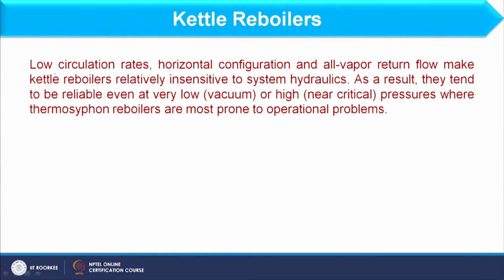So, these are some points about the kettle reboiler. Let us have more discussion about this. It has low circulation rates, and the horizontal configuration and all-vapor return flow make the kettle reboiler relatively insensitive to system hydraulics.